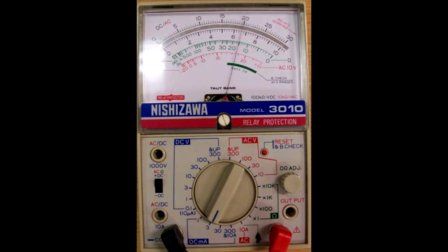In this example, we have the meter set to a range of 3 milliamps. So you find what scale you're using, that would be the top blue one, and since there is no 3 scale, we'll be dividing everything on the top scale by 10 to get it down to 3. So in this example, we have a current reading of 2 milliamps. I hope this final example helped understand how to use an analog meter, because it can be one of the more difficult things, but with practice it's easy to understand.